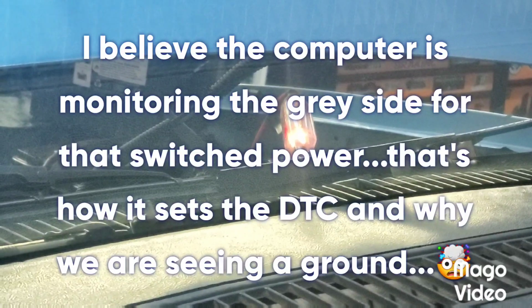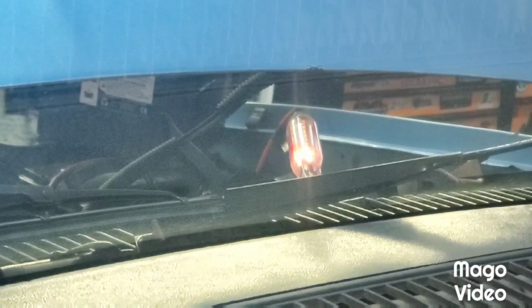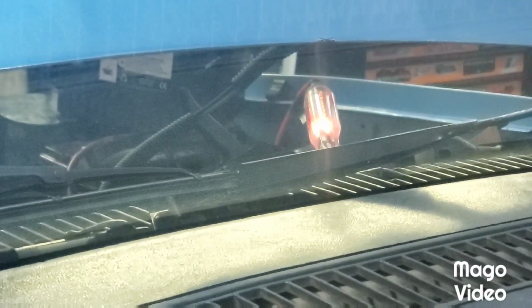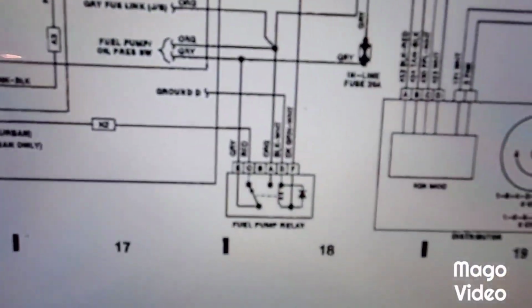Okay, key's off and it's a full-time ground. Let me cycle it on. That light should be going out right now with the prime, and it's not, because that should have just turned into a power feed. Let's crank it. Now we've got a no start. Now watch this. Key off, key on. There, it's working. Starts right up. It's intermittent. It is a fuel pump relay problem, no doubt about it.